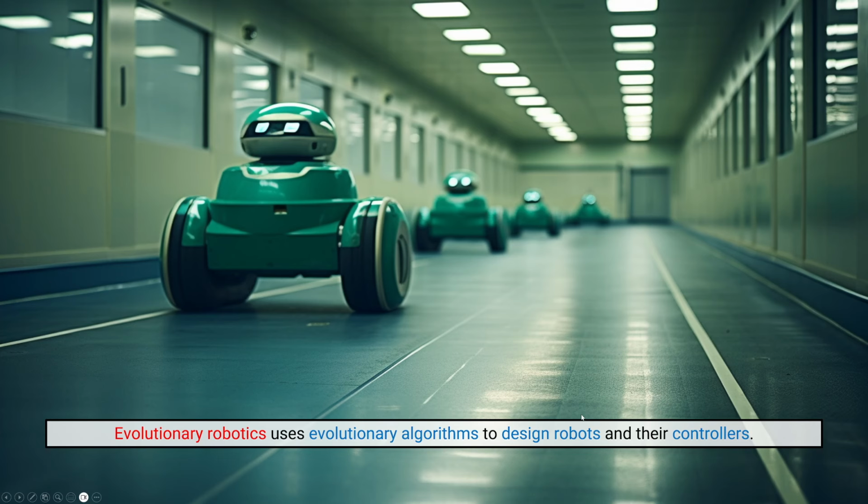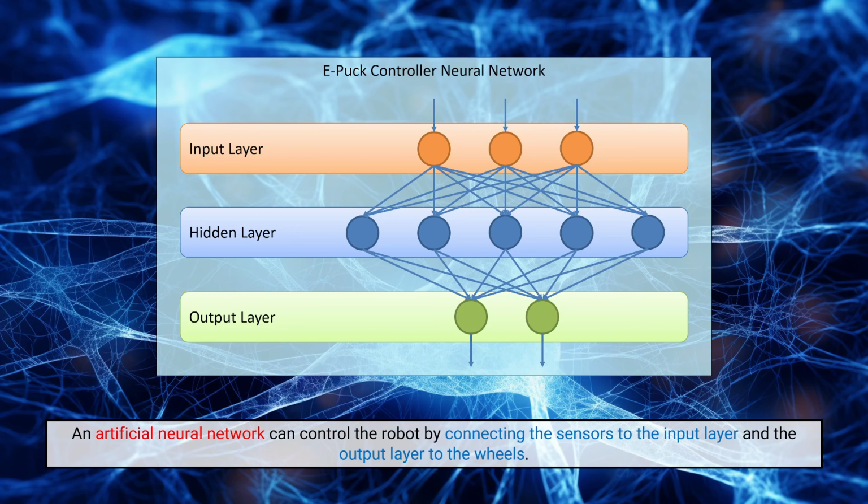So for instance, here's maybe a very simple example, overly simplified just to make my diagram a little bit easier and tidier to view. But let's imagine that we've got an Epuck controller neural network. Here I have built just a simple one. And we can imagine, to start out, that the output layer, these two output neurons, are connected to our left and our right wheel for our robot. And then our input layer, I've only got 3 input neurons indicated here. Again, just for simplicity, it's very common that we're going to have considerably more input neurons.